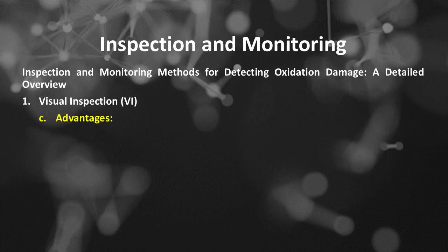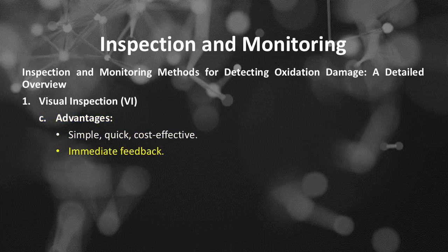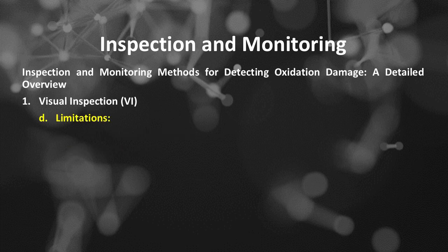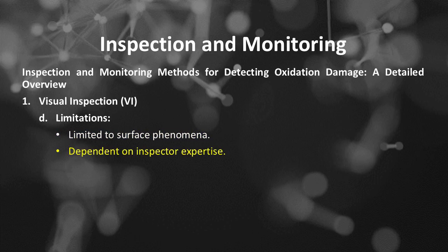Visual inspection advantages include being simple, quick, cost-effective, with immediate feedback. Visual inspection limitations include being limited to surface phenomena, dependent on inspector expertise, and unable to detect subsurface or internal damage.